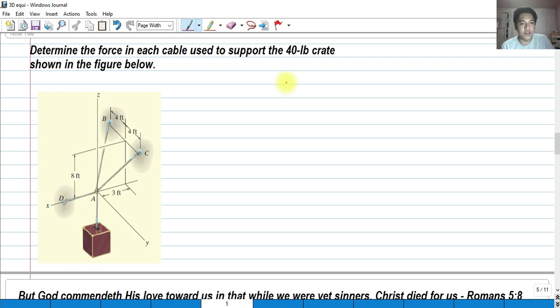Okay, still, we don't know the forces. We are going to represent the forces using Cartesian vectors. So let's try to get F sub B first. The force F sub B equals the scalar component of FB, which is multiplied by the unit vector in the direction of FB. So we have to write the unit vector of that.